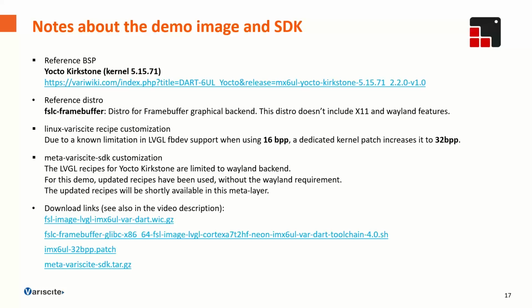We made very minor customization of the kernel that will not be present by default. I'm referring to the 16 bits per pixel that by default we have in our BSP. The 6UL being targeted at low resource applications, to save memory, we use the FrameBuffer with 16 bits per pixel.